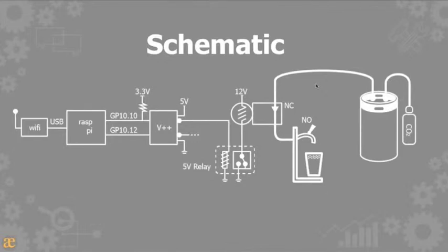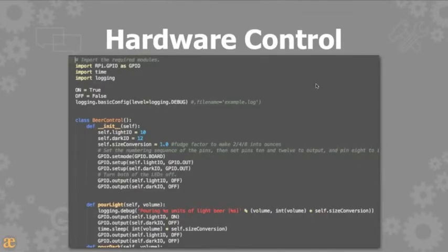That caused the logic pin to drive high, which triggered the NPN transistor, which turned on the relay, which hooked up the solenoid between 12 volts and ground, so it allowed electricity to flow through that coil, which then activated the solenoid check valve and allowed beer to flow through the system. So that's how the whole thing works, if you followed any of that.